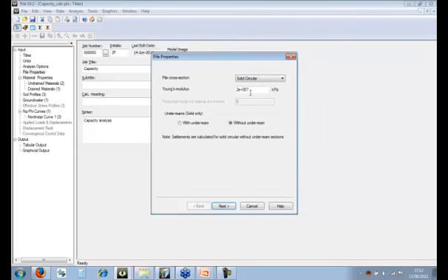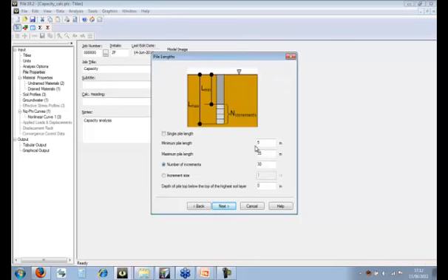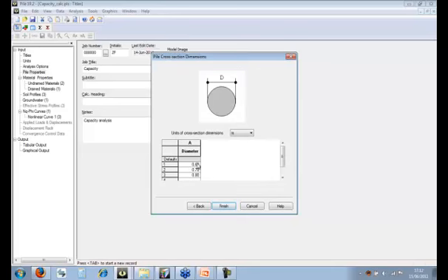We've got the pile properties in here, and this is interesting because, as you can see, there are a number of options of piles: solid circular, solid square, hollow circular, hollow square, and H piles. You've got with or without underream. As opposed to just considering one single pile length, it'll consider a range of lengths, a minimum and a maximum, so you can look at your values at different levels, and that's quite helpful. And also, beyond that, you can choose more than one pile diameter. So for example, if you're taking some pile capacity charts, if you're looking at structural loads and trying to decide what kind of piles you'll use, this kind of thing is pretty helpful, and that's also available in Pile.